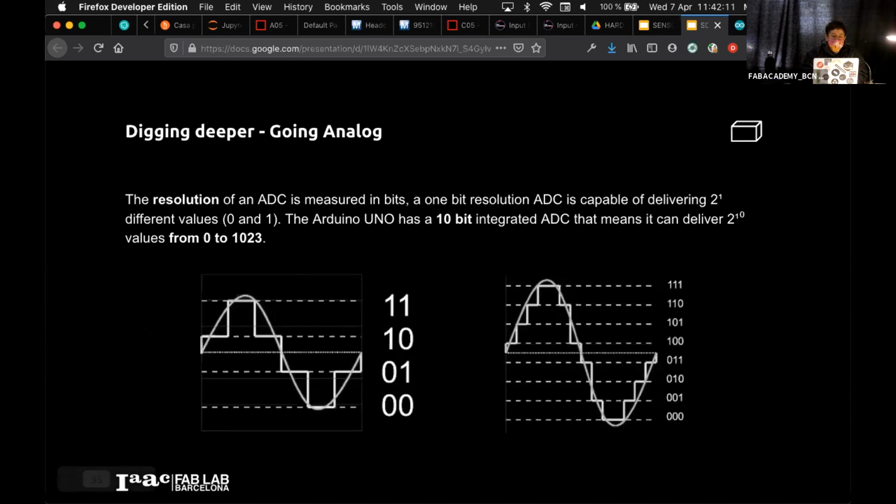That will basically fall into these different buckets of our ADC. And of course, as we talked about, depending on the resolution or the number of binary values that I can put here, I'm going to get better accuracy or a better representation of our signal. But basically what we are doing is this sine wave that I have on the left.